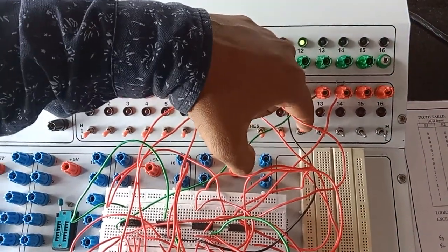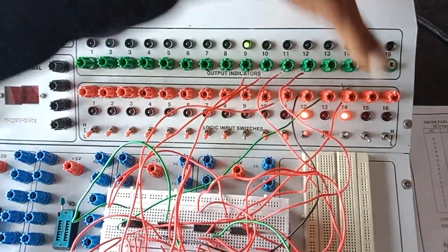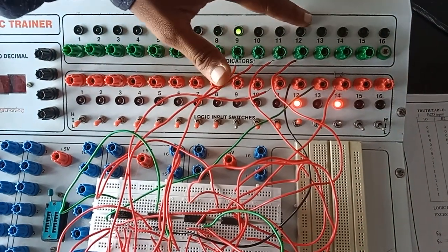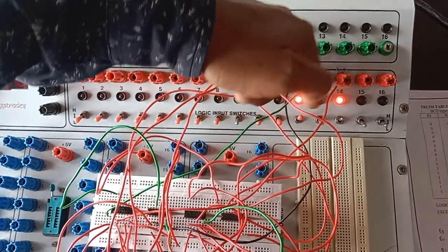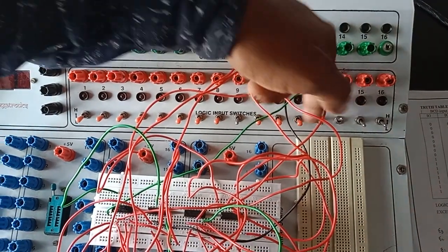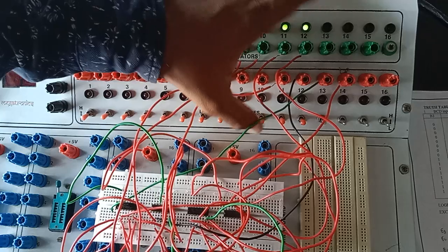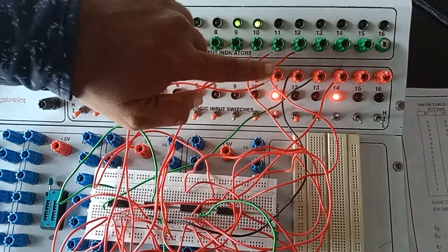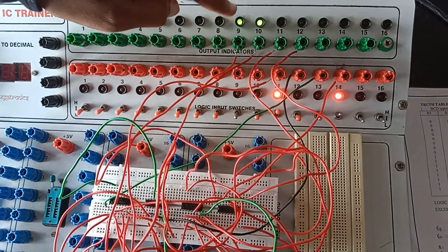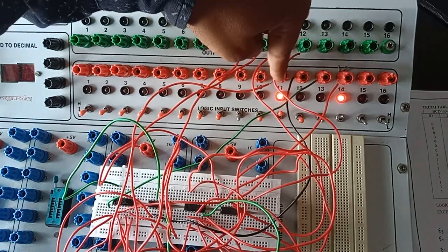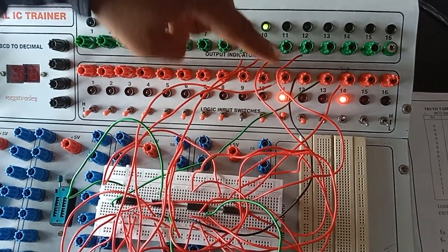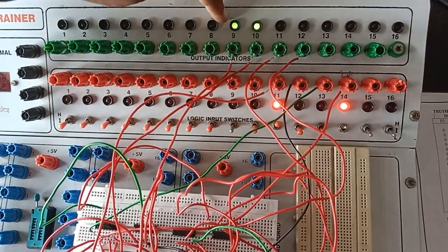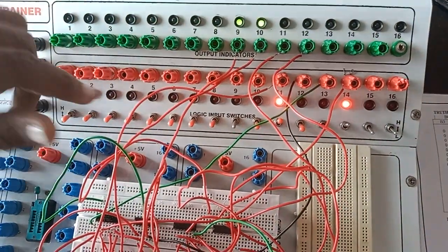So next case, if you give the input as 5, that is 5 plus 3 is 8, so 1 0 0 0. The last case I am going to verify is the input 9. So this is input 8 and 9. Sorry, input is 9, that is 8 plus 1, 9. Input 9 means 9 plus 3 is 12. So this is 8 weightage, this is 4 weightage. So 8 plus 4 is 12. So if the input is 9, the output is 12.